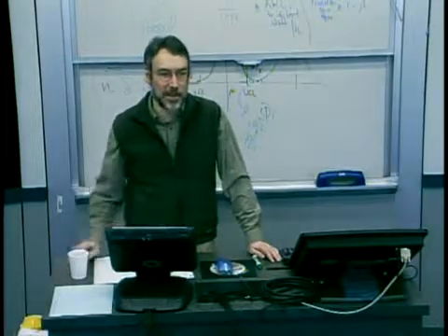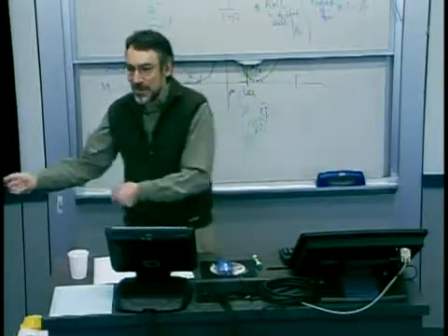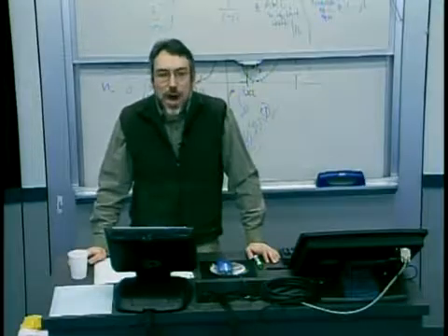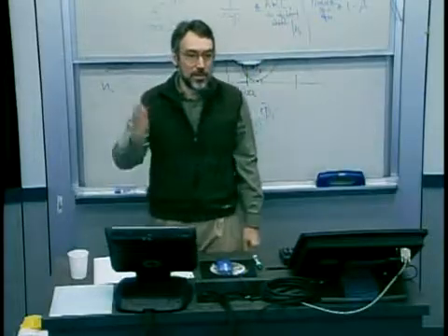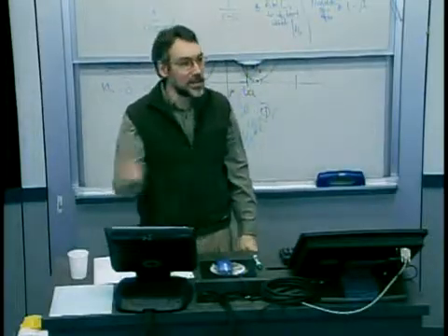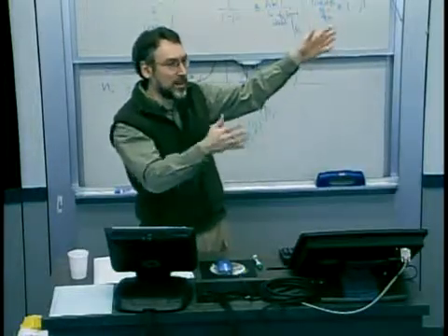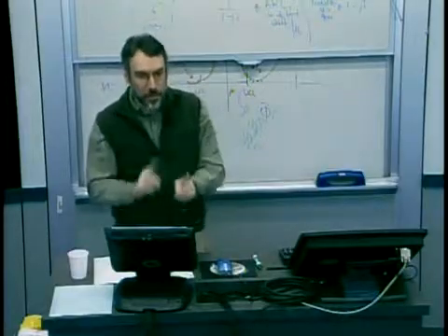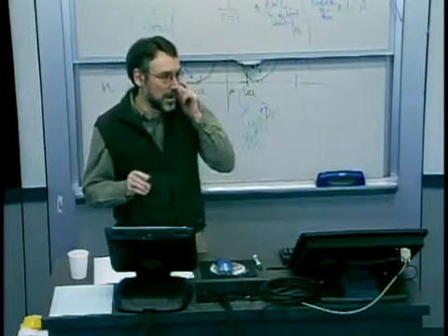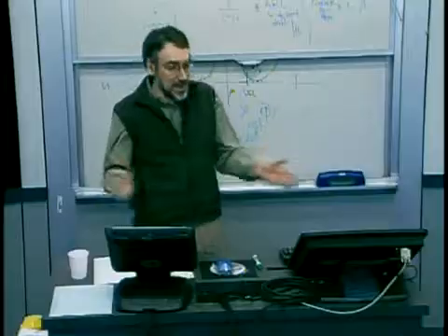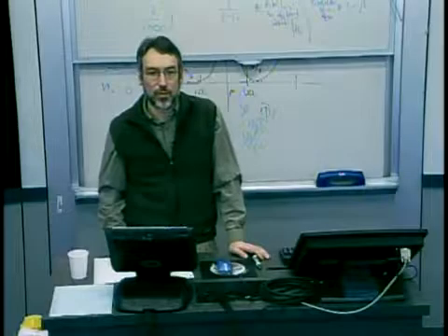I'll tell you the number one thing I would do. Look at the screen. Pull the power plug, plug it back in. No. I would, yes. Check the measurement equipment. Yes, that's exactly what I would do. I would always doubt my measurement equipment first. They also have failures. Rather than pull the process, turn the process off and panic with the actual equipment, I'd want to verify the measurement first. So I'd take it off, do an independent measurement of those parts and try to understand it. So let's say that indeed I see, yes, that part looks like it's outside of the control limits.